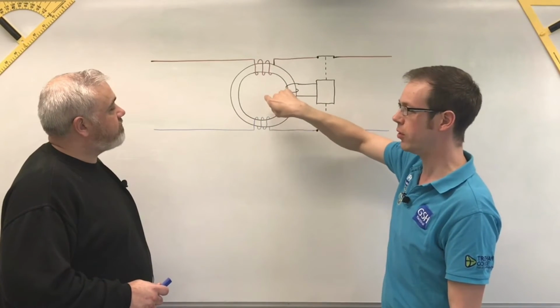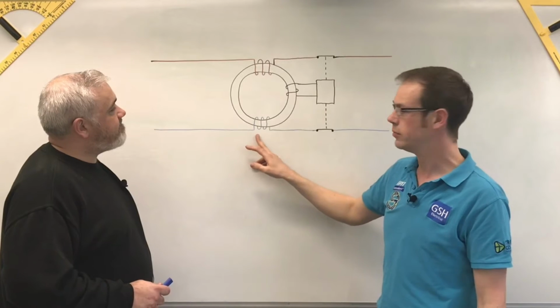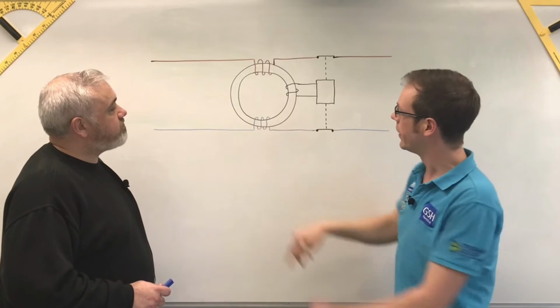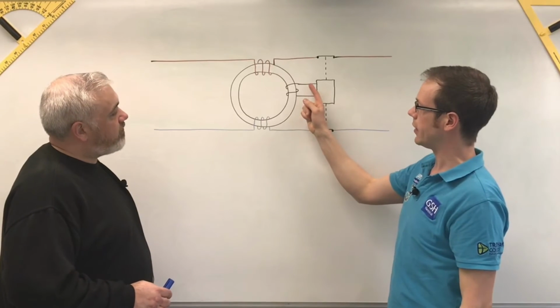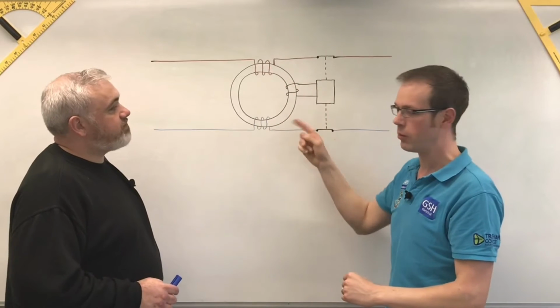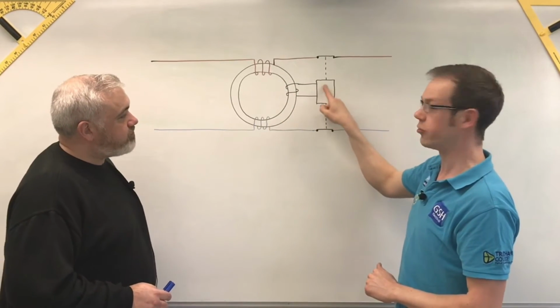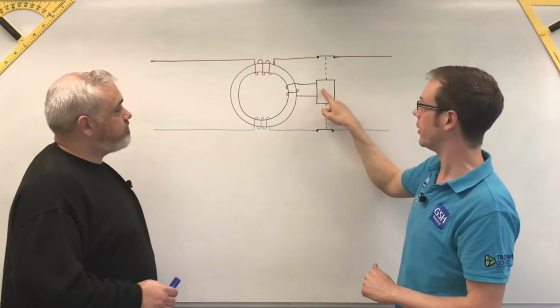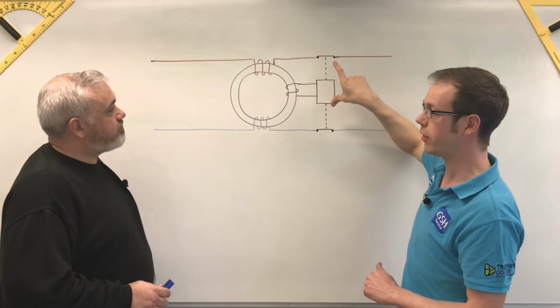Sometimes it goes straight through the middle, but the principle is exactly the same. And then the return path of the neutral is behaving in the same way. And then wrapped around this side of the iron core, we've got a small loop here, again, inside an actual RCD. This might be looped around many times, but we've just simplified it here. And that's what communicates with the little tripping device inside the RCBO or the RCD, which is going to disconnect the circuit under fault conditions, we hope.